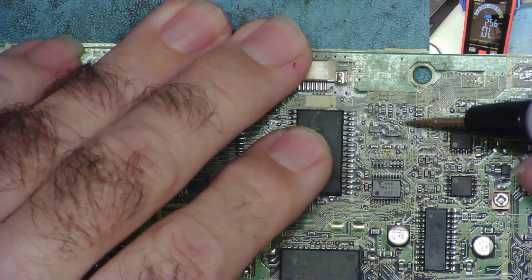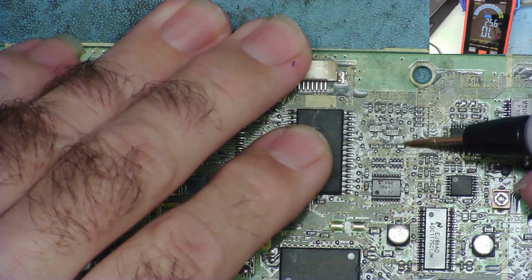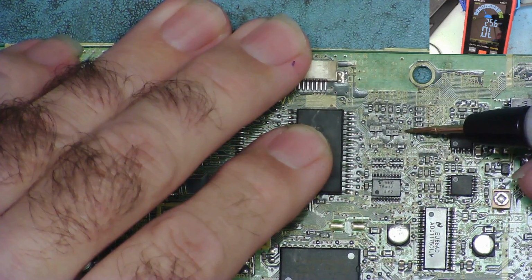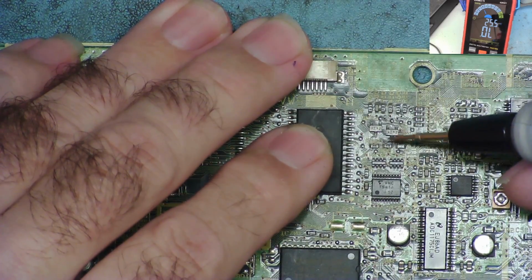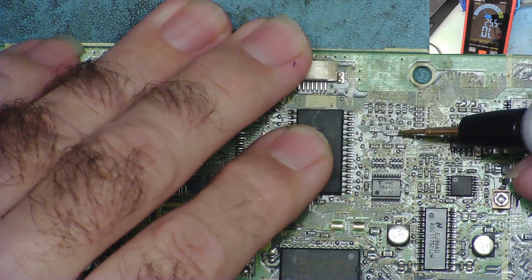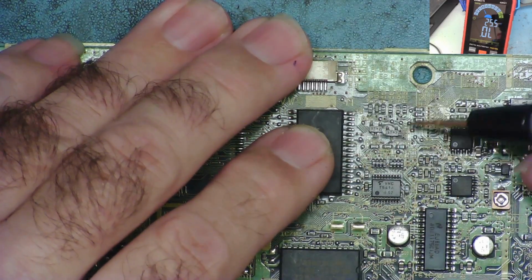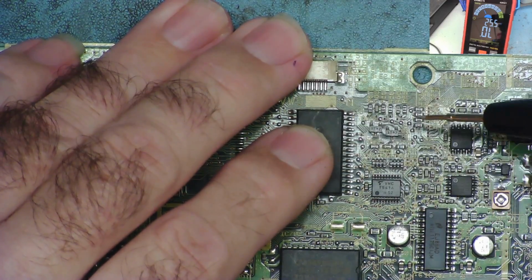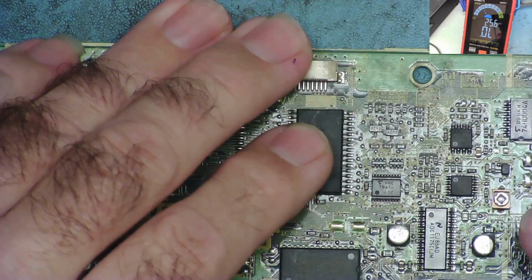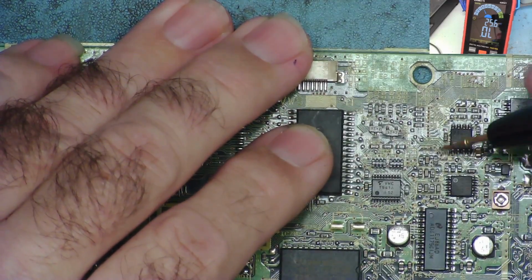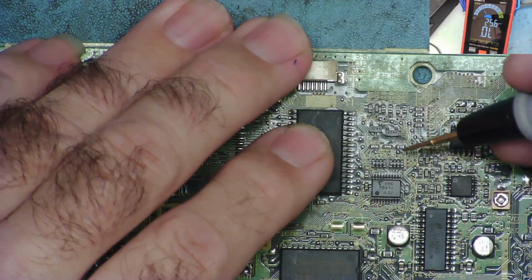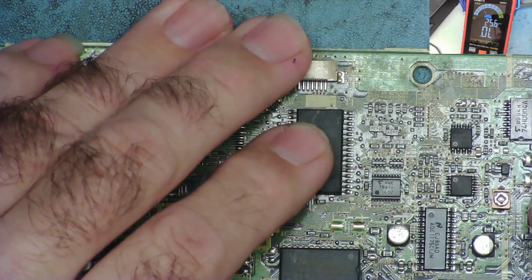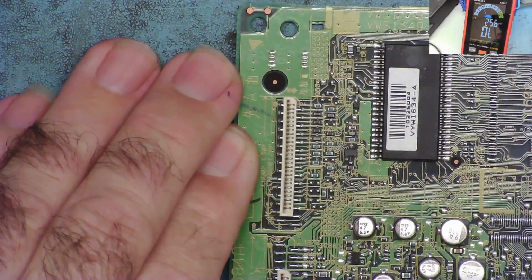But via that method, so SMD code SOT-23 or SOT space 23, yeah? And that will probably find you the part number. Now, once you get the part number from the code, you can then look up the data sheet and figure out what that actually is. The other possibility is just to take it off the board. They're quite easy to unsolder. You may have to tag some little wires on it and use a components analyzer and see what it is, yeah? So that's one.